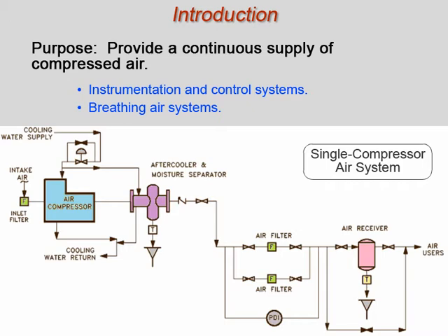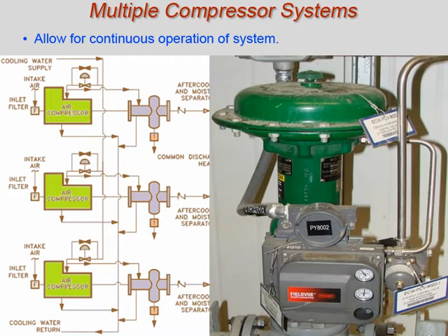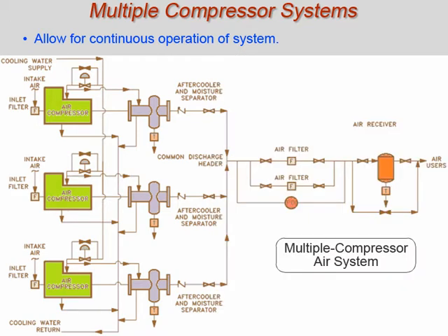Compressor systems consist of one or more air compressors. Normally, a single compressor can supply one or more systems with compressed air. One of the most important uses of compressed air is for indication and control of process and support systems at LWO. For example, the numerous heating, ventilation, and air conditioning (HVAC) systems are controlled almost exclusively by air-operated actuators. These systems would not function without a dependable supply of clean compressed air at the proper pressure.